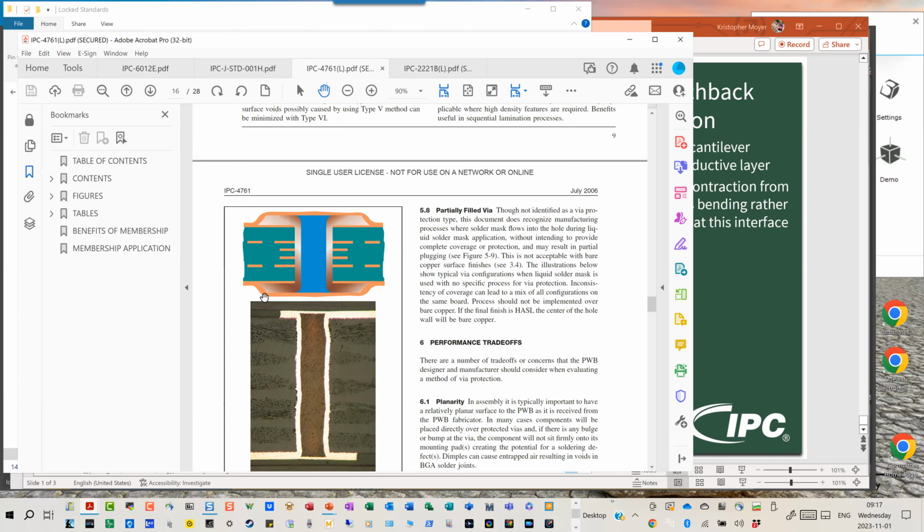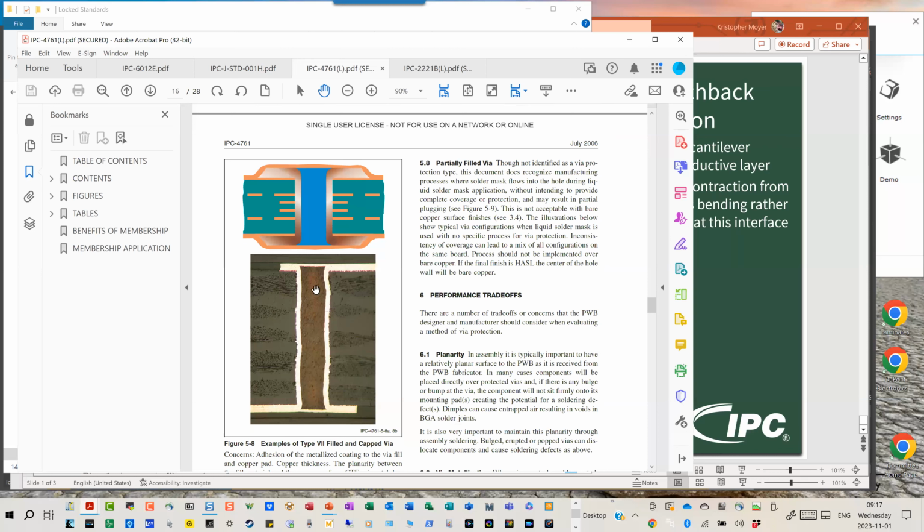This type I use quite frequently and in fact is necessary when we're doing stacked microvias. We're already seeing that in our design a little bit where I have the microvia stacked on a buried via with another microvia. So if I need to do that microvia, I need to have this metallized surface right here for the microvia to connect to. So we will plug and fill. Again, can be conductive or non-conductive. And then we will go and do the capping and planarization with a metallization.